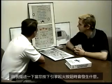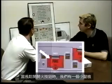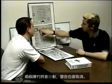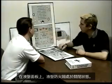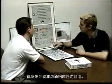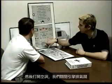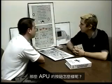Describe to me what occurs when you select an engine fire push button. When I release that fire push button, we have a little gouge we use, which is 21212. On the top, we start with 2. The 2 squibs are going to be armed, as well as the warning is going to be canceled. On the hydraulic panel, the hydraulic fire shutoff valve is closed. On the fuel panel, we've got 2 things. The low pressure fuel valve is closed, as well as the fuel return valve. On the electrical, we deactivate the generator, and then on the air conditioning, we close the engine bleed valve and the associated pack valve. What about for the APU fire push button?